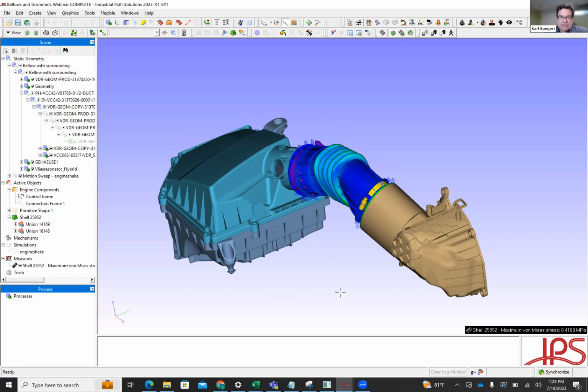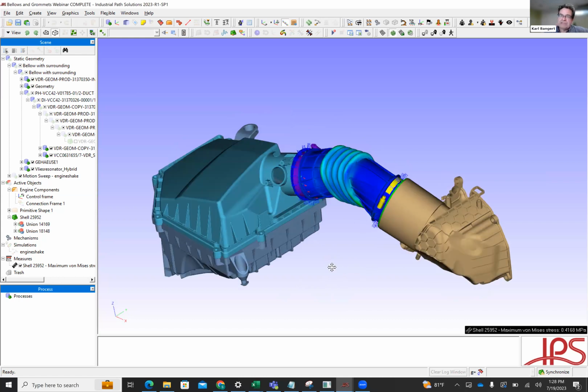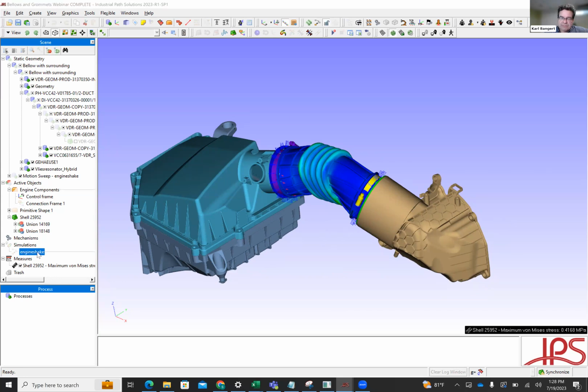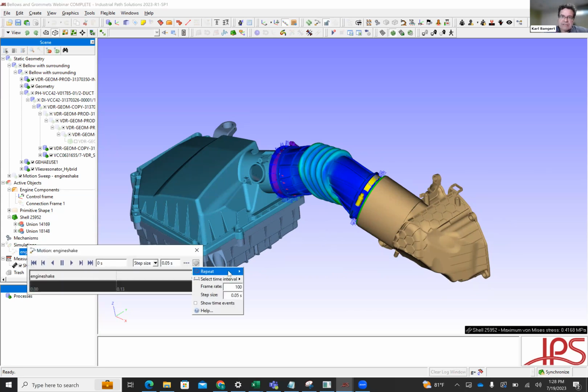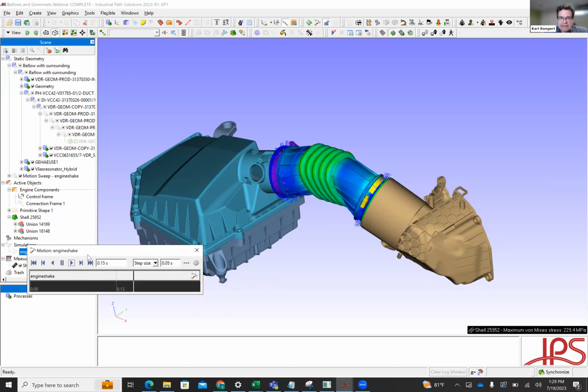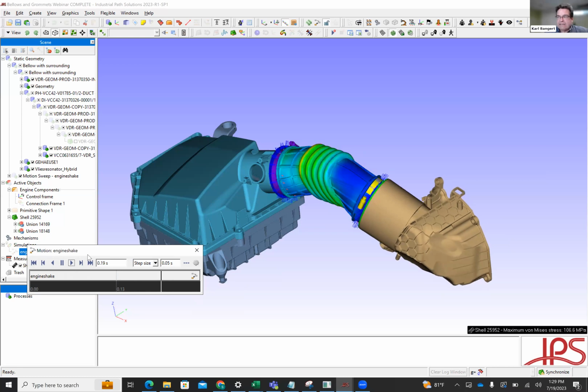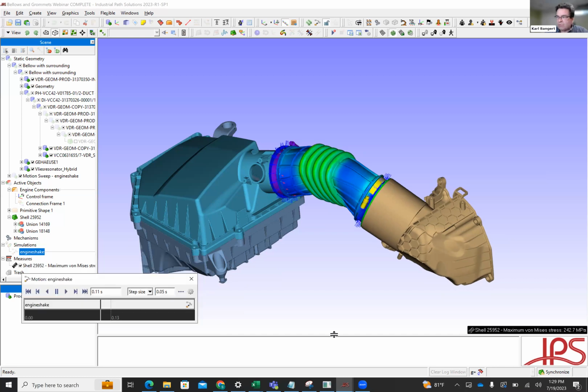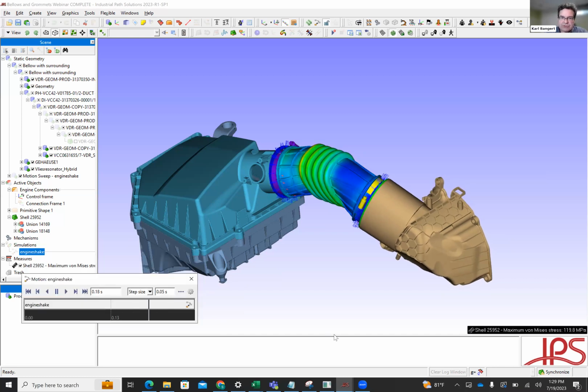I would mention also to folks that are listening that additional features under development include being able to apply an interior pressure to the bellows. So if you've got a net positive or negative pressure, that would be taken into account. There's work being done to include stiffening rings as well, and then also to handle complex wire and cable grommet interactions, different types of geometry there.